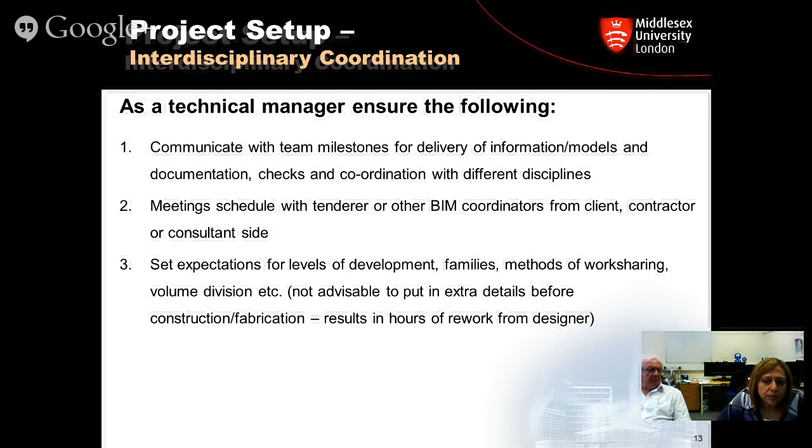All right, it also would be very good and convenient if in the team you decide on what LODs, levels of development, detail, definition, we will talk about the LOD thing later on, are to be used on which models or on which parts of the models, because within the same model, you might have an object that is at an LOD which is different from another object, and it does happen, okay? The whole model doesn't have to be at the same LOD. What kind of families are going to be created? How the work sharing is going to happen, so who is responsible for what volumes, at what times of the day, what times of the week, and how will the coordination happen at the end of each week, for example, the volume division, as I said.